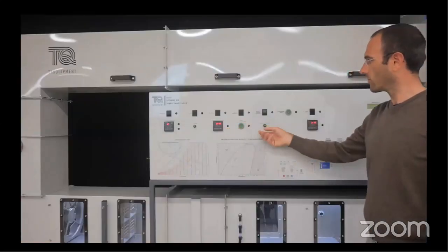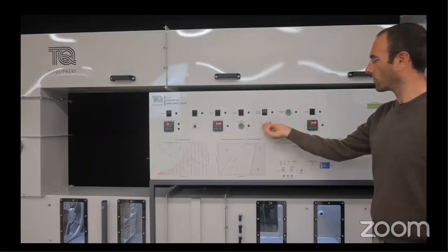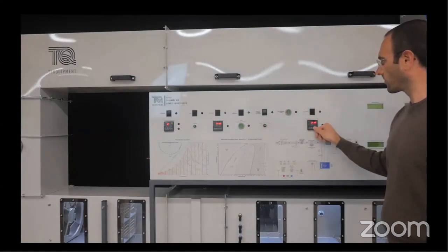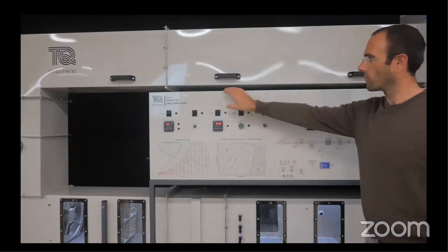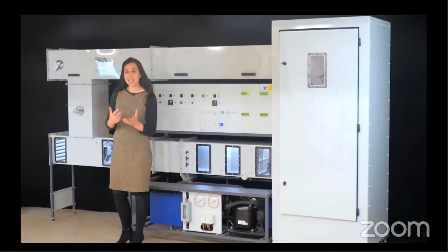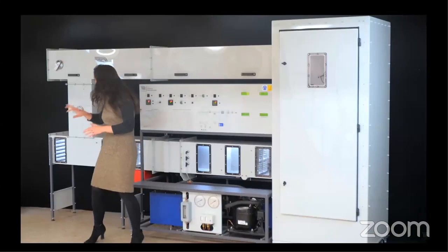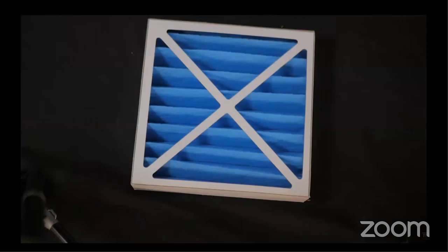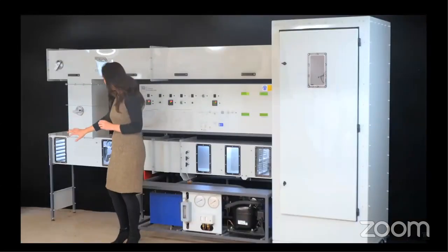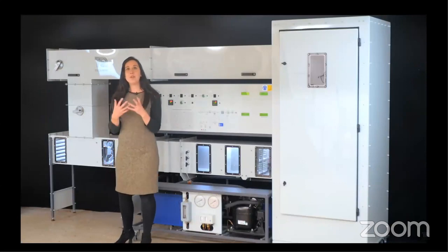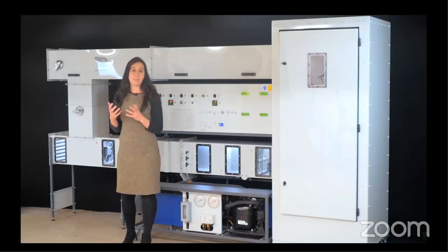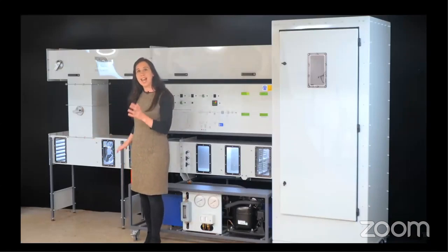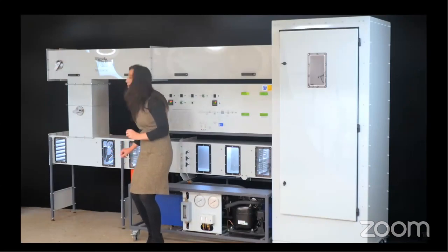At the core, the base unit includes the control panel. This has all the control functionality for changing the airflow velocity, temperature, water flow rates, and has the VDAS on board included as well. Onto the air handling unit, which attaches to the base unit. Starting over here, the air enters the unit through a grill with a filter and dampener in the air intake control area. Just a little along is the variable speed fan that can move at a maximum of 1200 cubic meters per hour.